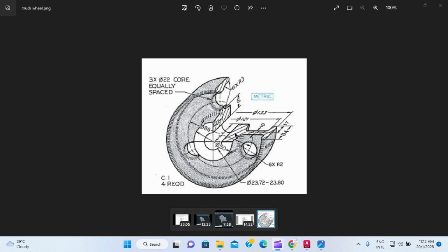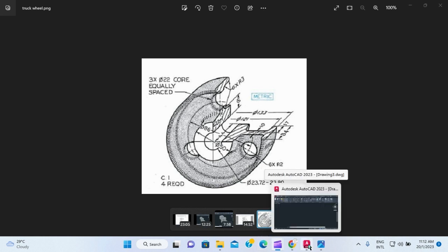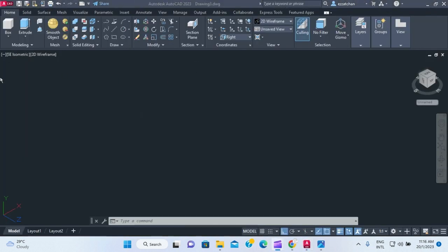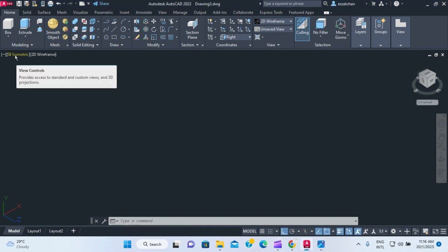from here to here is 54.6, and then this part is about 13.1, based on the difference between the diameter from this side and this side. And it will revolve around this diameter in the center here. So I'm going to quickly draw this part and then let it revolve around. Okay, let's now quickly draw the thing that we mentioned just now.